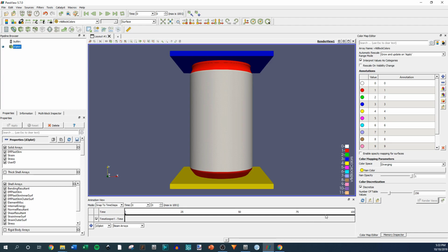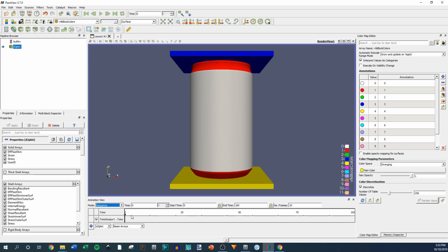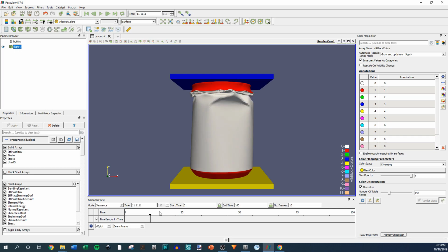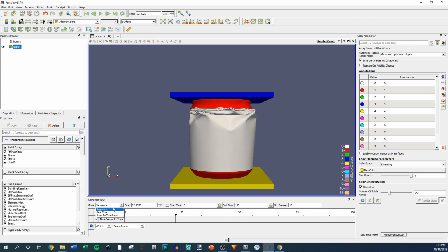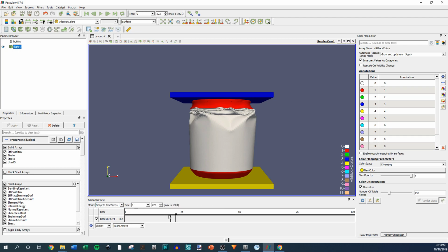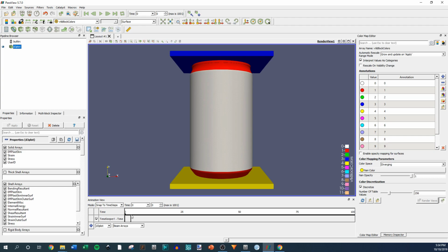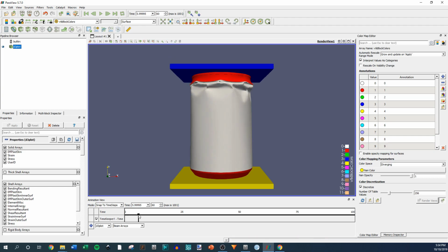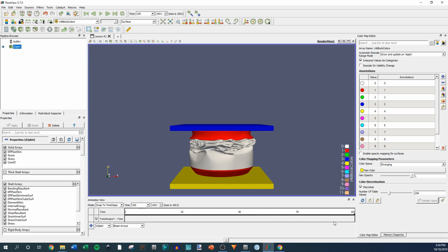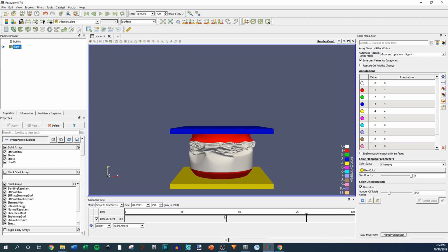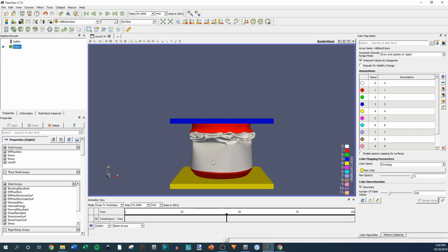So down here is your timeline. And I'm not an expert in Paraview by any stretch of the imagination. I'm just trying to help you get good looking videos, and I'm going to do that. This is your timeline, and your millisecond range is what I'm in, so 0 to 100, that's how long the simulation is. And you can change this. This is snap to time steps. This was a very fine animation I made, so there's a ton of time steps, 1,000 time steps, however you want to say it. But you see, you're still restricted by this mesh. So we want to change that.